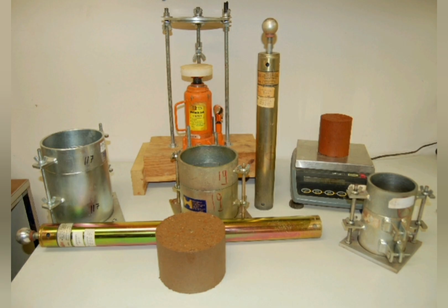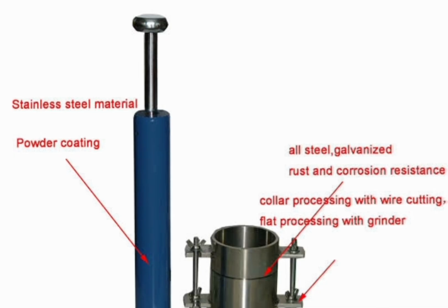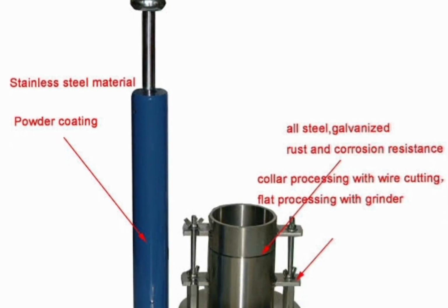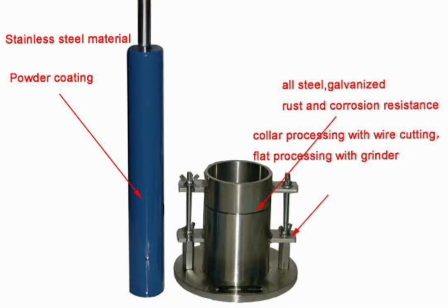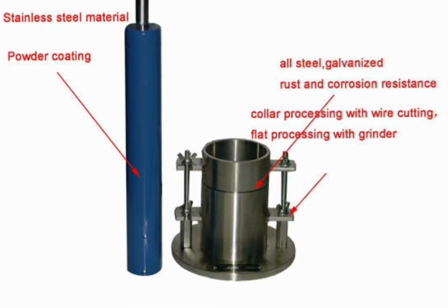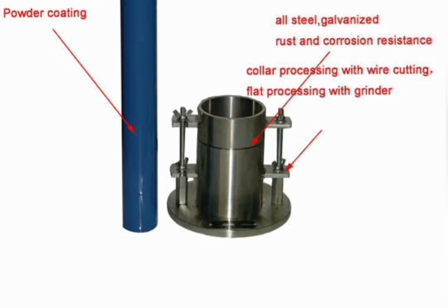We measure the wet density of the compacted soil. We then break off a piece to determine its exact water content, which allows us to calculate the dry density. We repeat this process with the same soil, but at incrementally higher water contents. When we plot the dry density against the water content, we get a curve that peaks at a point called the maximum dry density, MDD, at an optimum moisture content, OMC. This is our recipe for the densest, strongest possible soil. In the field, we use a nuclear density gauge to check if we've achieved, say, 95% of this maximum dry density.